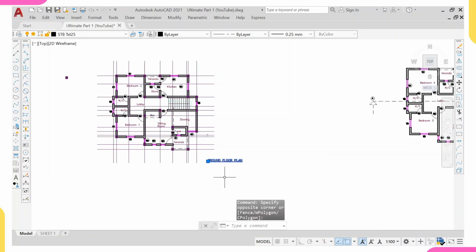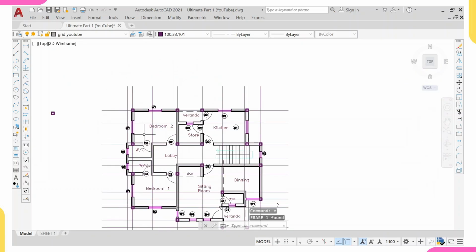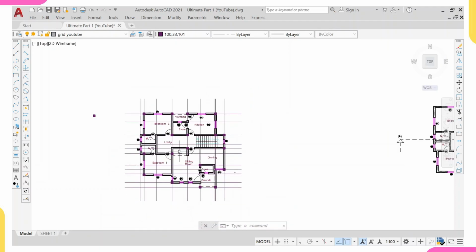So I'll click on this, I'll delete this. It's not necessary, I don't want it. So let's continue. So paneling, we say that paneling should not be more than 30 meter square area. So if your paneling is more than 30 meter square area, what you do is that you either increase the depth from 150 to 175, or you break that panel with a beam. Don't worry, let's continue. I will show you the example.